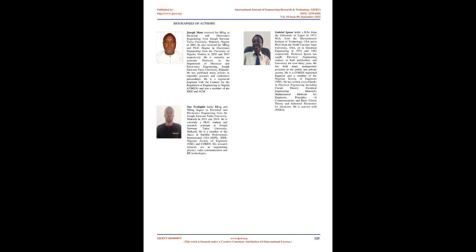RMS values obtained from Table 7 suggest that the RMS of the existing ITU model was 75.504 for rain rate value 100 mm/h. The resulting RMS value has been reduced by the modified ITU-R model to 64.2617. Results further suggest that for rain rates ranging 20 to 100 mm/h, the modified ITU-R model reduced the RMS error value by at least 5.46135%. Conclusion. In this study, a modification to the existing ITU-R P.530-17 rain attenuation prediction technique has been developed.